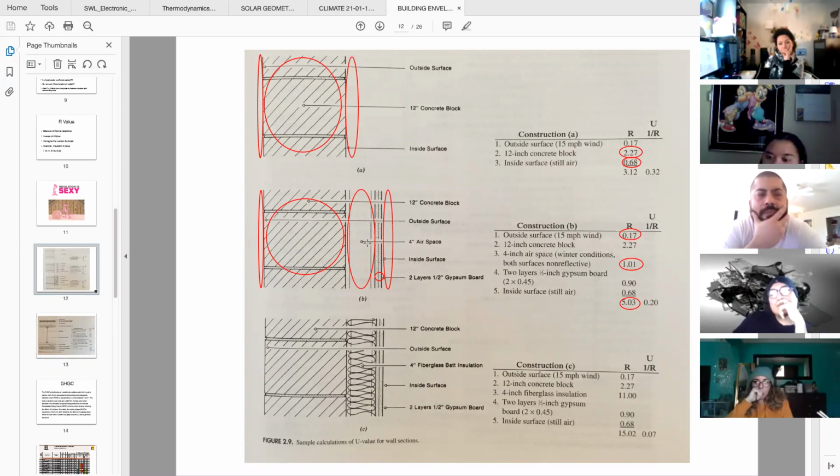Because most studs are 16 inches on center for a wall or a ceiling, or 24 for a roof, they're negligible in the overall surface area of the wall. So if you're looking at a 10 by 10 square foot wall with this many layers in it, the metal stud or the wood stud, that distance, when you add up all those studs, is negligible in the overall performance.